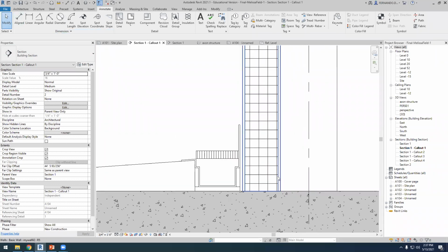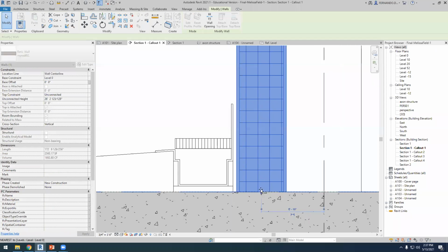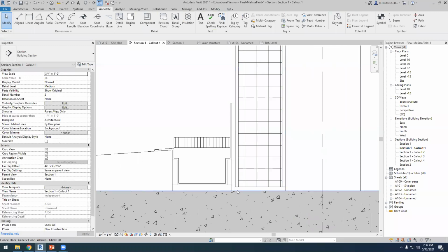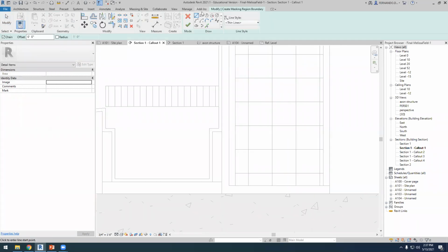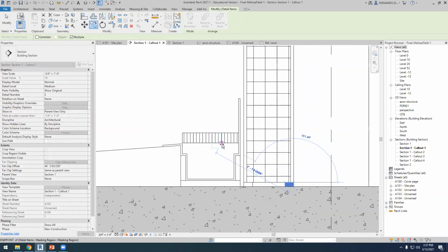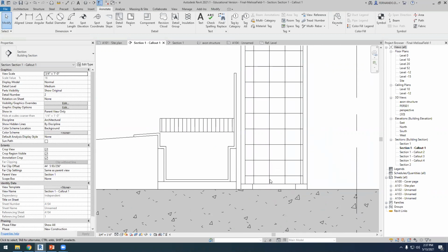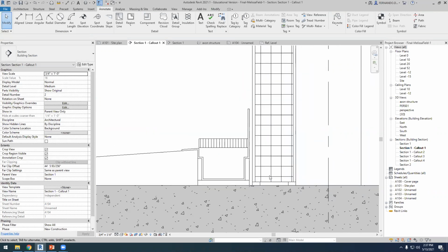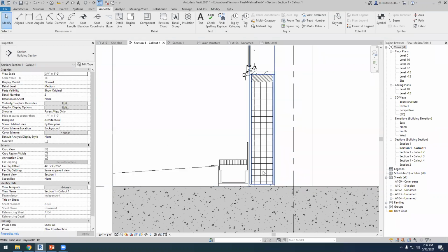So first, I would lift this wall just a little to create a gap here, and then I'll fill this gap with some silicone. We're going to need another structural element here because we are ending this wall and it can't end with rigid insulation.